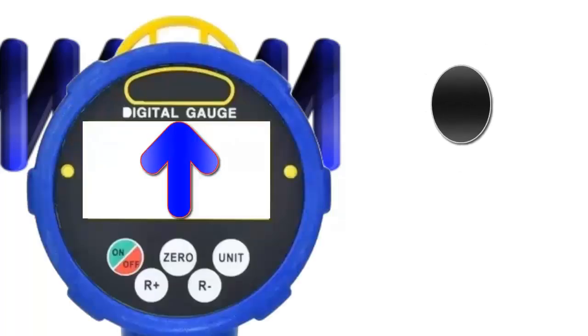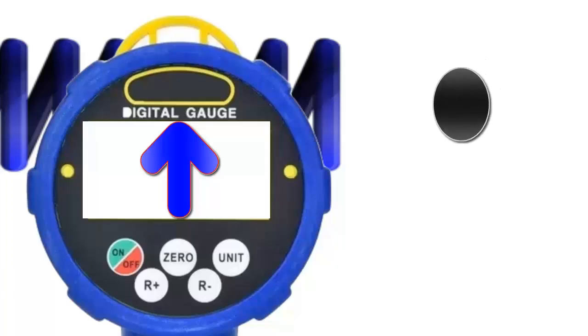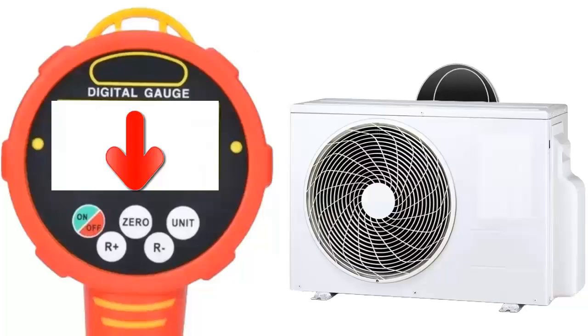Case 3. Capillary tube with a larger diameter than required. Now, keeping the capillary tube length fixed but increasing its diameter, we observe that the low pressure side is most affected. Although high pressure may also experience some variation, the most significant change occurs in low pressure, which can drop to critical levels. In extreme cases, high pressure may not form properly due to the lack of restriction, preventing the necessary pressure differential from developing in the system.